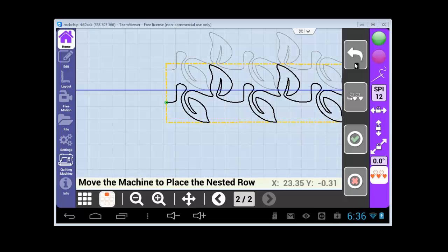the reason I'm bringing this up is, let's say you were going to nest like 14 or 15 of these patterns, or some absurd number, and you wanted to make sure that every row had the exact same spacing when you nested it. That's the feature you would use to do that. You would just manually go in there and hit that button, and it would automatically space it perfectly every time. Does that make sense?